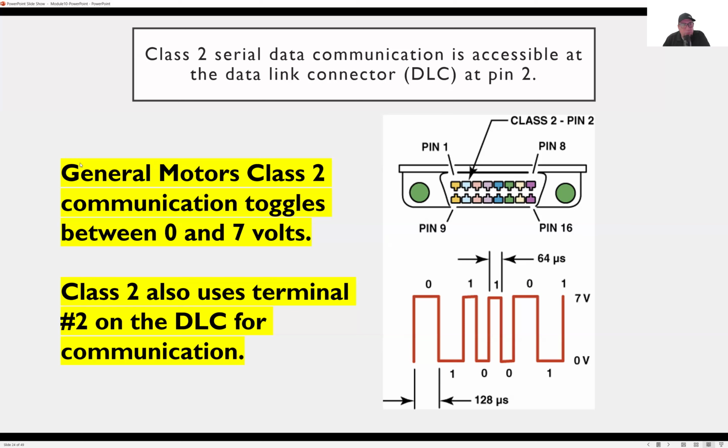And the OBD2 connector, which is here, which I just circled, has 16 pins on it. Pin number 16 is power. Pin number 4 is ground. Pin number 6 is also, wait, sorry. I want to make sure I get it right. Pin number 14, I believe, is ground or communication. Anyways, we've talked about this before, and this is something you can look up really easily. Look up DLC connector, and then you can type in pins, and they can tell you what they are. I know 16 and 4; those are the common ones. There's a couple other common ones too. I think it's 6 and 14 that are common on all vehicles.